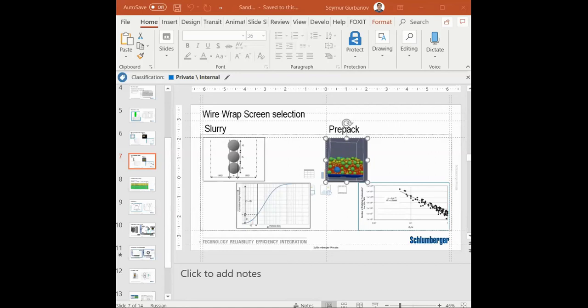You're just getting wrong results, wrong gravel, and this damages the reputation of the gravel pack most of the time. People do it the wrong way, and then they blame the gravel pack for not working. If properly selected, gravel pack will work. This technology was developed 80 years ago, and so far humanity hasn't developed something better than that. Maybe in the future we will have better solutions, but for now it's like that.